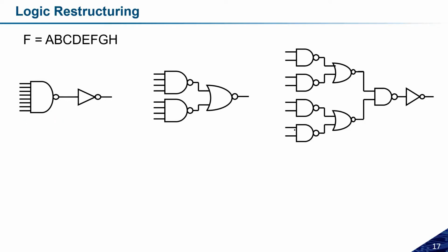But the problem is, suppose this particular circuit will have some delay. Let us assume all this circuit has some delay, T1 across all of these. So this NOR gate will act once it receives the output from this one and this one, and this will also have some delay. Let us assume T2. So the output at this point I can receive after T1 plus T2 time.